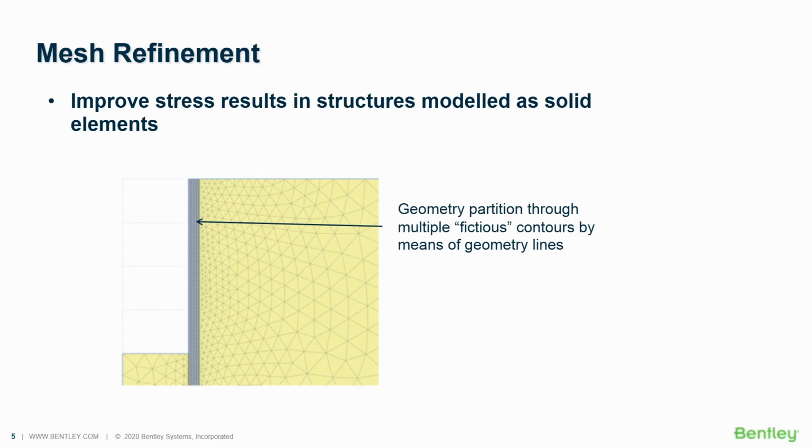This technique is sometimes called partitioning, and this is something I use almost systematically when modeling retaining walls as solid elements. So this is what is being suggested here.